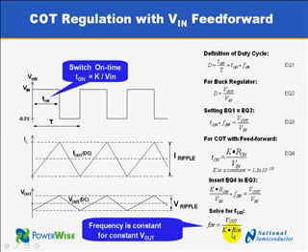So we see we get a switching frequency which is completely constant, independent of the load current or the input voltage. Of course, the VOUT is constant as well because we regulated it. So the R on sets the constant frequency.